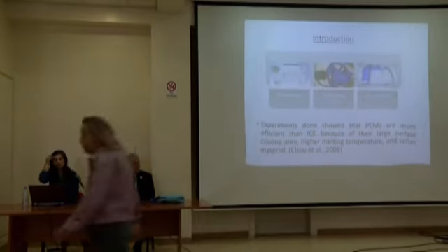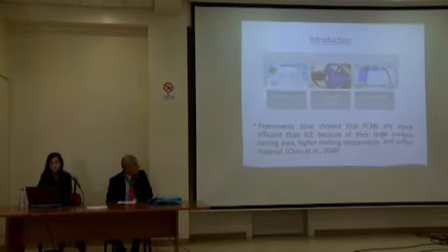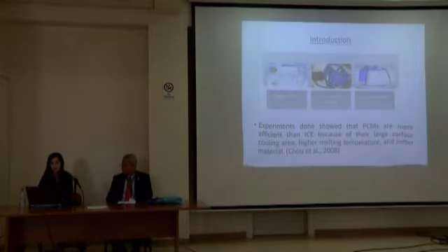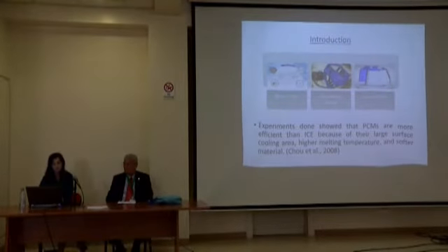So in order to improve the endurance of the workers under hot environments, passive cooling vests may be used. There are different types of these vests. The first one is a convective garment, and it contains a blower fan to force the air in the microclimate region. However, these types of garments have high power consumption and low cooling capacity. The other type of garment is the circulating liquid garment, and also it has a pump, and the pump will force the cold liquid to circulate in capillary tubes that are placed inside the vest. However, these kinds of vests are heavy.